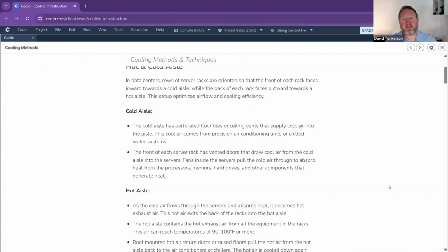One thing you will notice about data centers is that yes, there's loads and loads of heat produced in data centers, but every time you see a data center technician, they always come to work with a jumper or a jacket. And the reason for that is because we have cold aisles. Cold aisles is literally where all the cool air is being pumped into the systems. It normally comes up through a perforated floor.